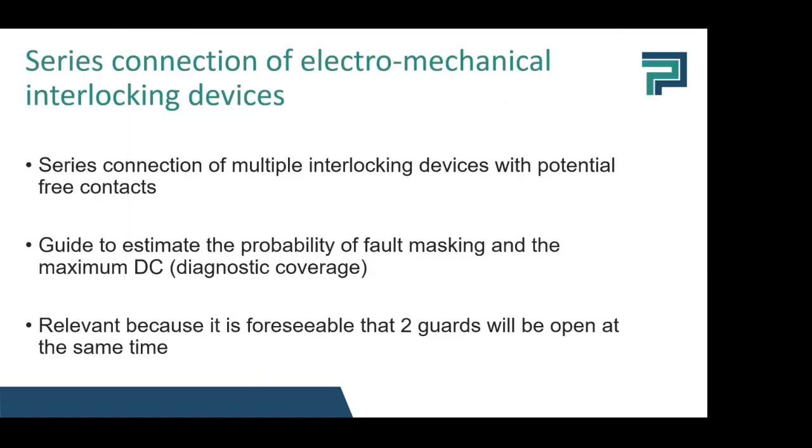Okay, so series connection of interlocking devices. This is only relevant for interlocking devices with potential free contacts, so no OSSD outputs, only potential free contacts.